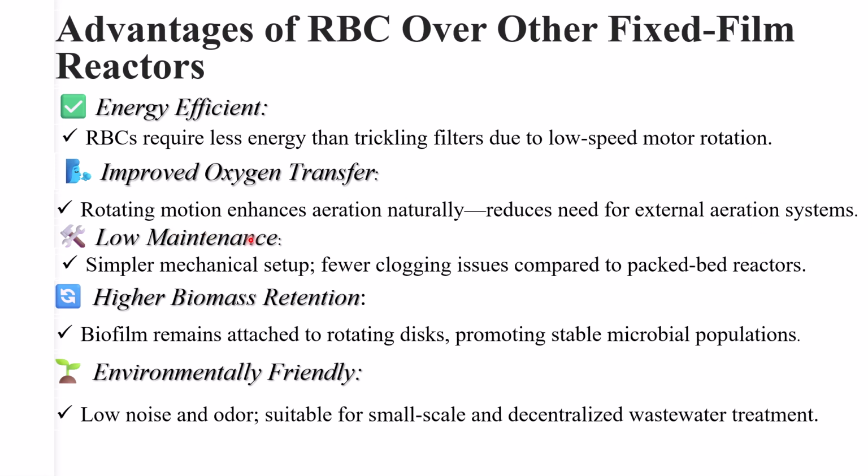The second is low maintenance. The simple mechanical setup allows fewer clogging issues compared to packed bed reactors. The third is higher biomass retention. Due to this, the formed sludge is very less in quantity. The biofilm remains attached to the rotating disc, promoting a stable microbial population. This is environment friendly. This ensures low noise and odor, and is suitable for small scale and decentralized wastewater treatment. The compact design is perfect for urban and rural areas.